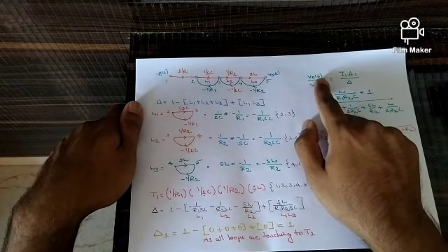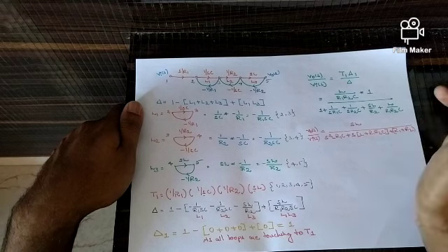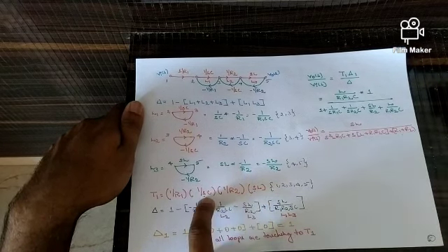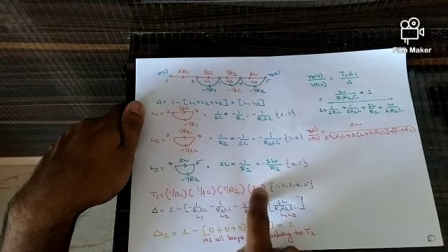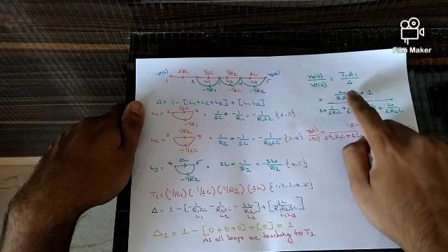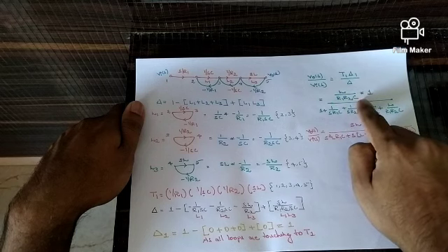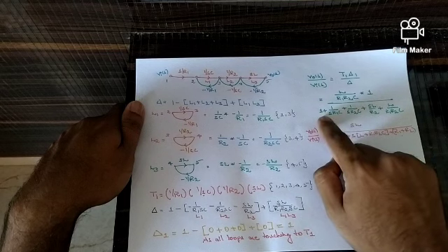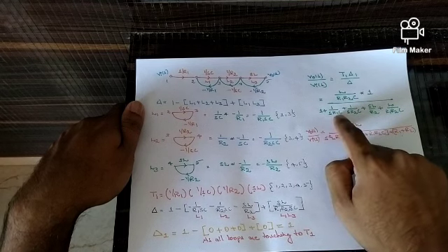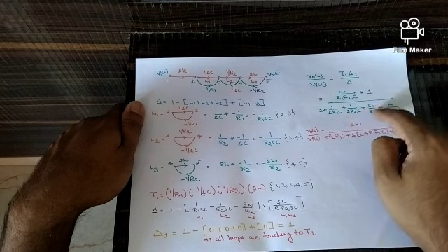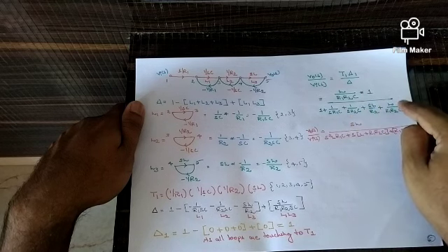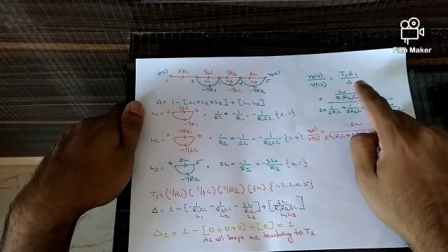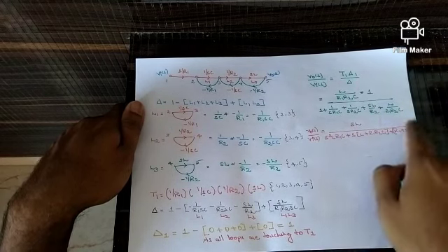So what is this? Now I just need to substitute all the values that I know. In this case I have S, again in the denominator I have an S. So these two get cancelled. What is left is T1, which is L divided by R1 R2 C, multiplied by delta 1, which is nothing but 1, divided by 1 plus 1 divided by SR1C plus 1 divided by SR2C plus SL by R2 plus L by R1 R2 C. If I solve this equation, I get the final answer like this.